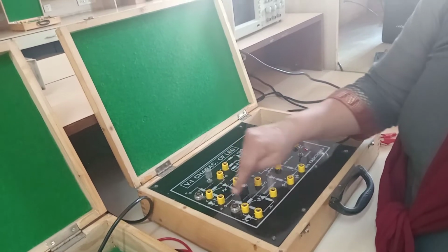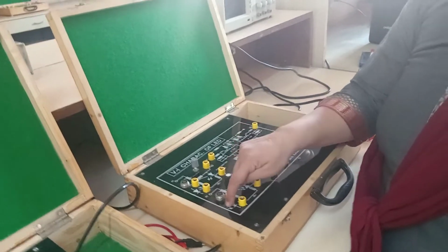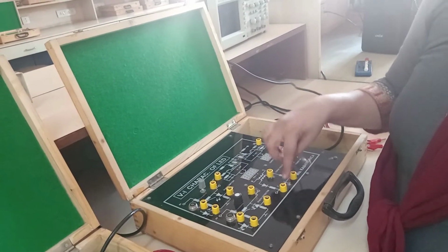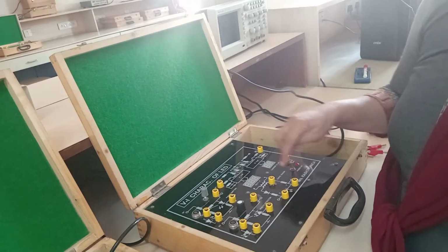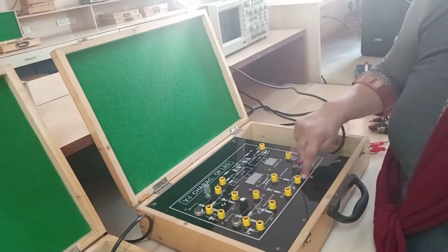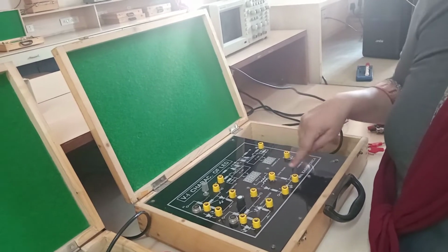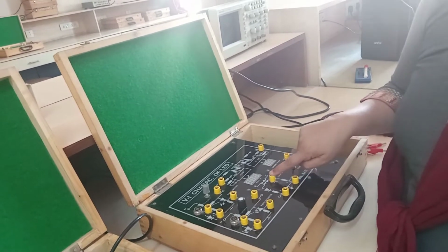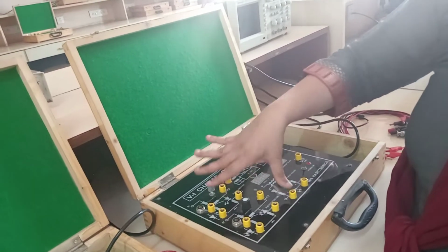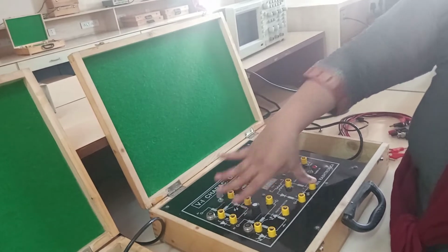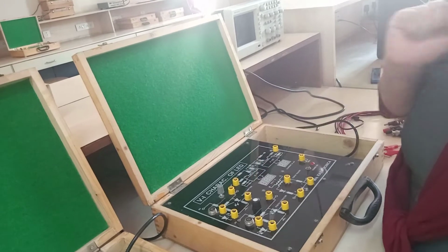Now why are these made isolated? Since we can check these detectors so that we can observe the VI characteristics of LEDs on the DSO, and for that a separate circuit is provided, that is a curve tracer with the transformer, and this is a separate ground for the curve tracer of the DSO. Over here individually you are supposed to connect the anode to anode and cathode to cathode. So first we should check the LEDs and then we should proceed for the experiment.